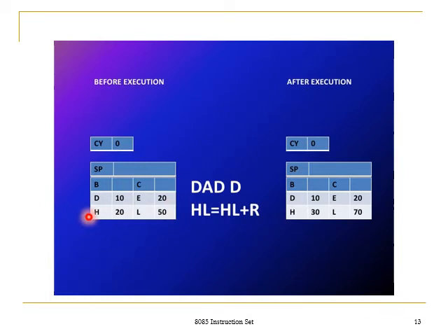Since the 8085 is an 8-bit microprocessor, it performs this 16-bit addition by first checking the least significant bytes of the 16-bit numbers. For this example, the least significant bytes are stored in the E register and L register.